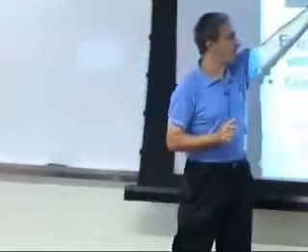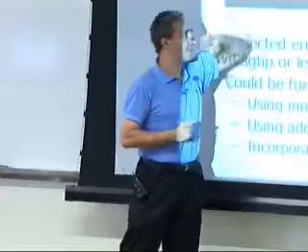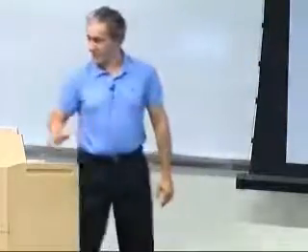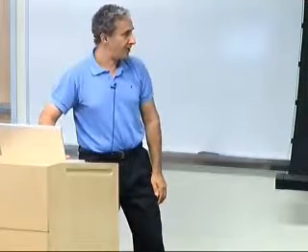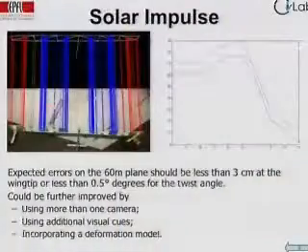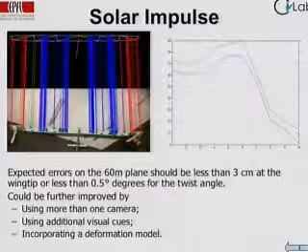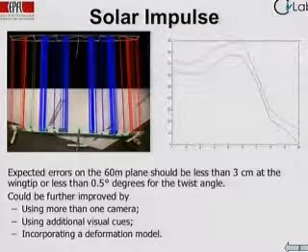So the idea is this is a slow flying plane, so we can imagine, at least for the initial flight tests, to have a car in front, and it flies slowly. So that looks at it from below, which is kind of this view. We've simulated that in the lab. That's about what you would see. The deformations here are grad student induced deformations, but the green thing is the outline of the wing that the algorithm computes by following the outline of the wings. And the curves on the right side are measures, I think it's the height of the wingtip with respect to some reference.